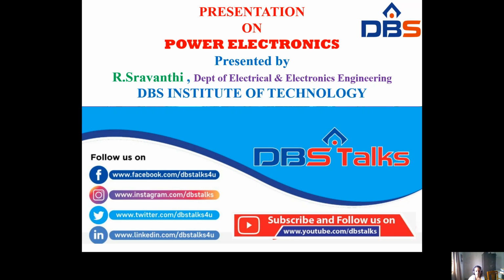Half-wave controlled converter with RLE load and a freewheeling diode. Here you have to see this diagram. Okay. Here single phase half wave control. So half wave control means the circuit diagram will have two thyristors and two diodes. And this is a freewheeling diode and the load will be RLE. Okay, so resistance, inductance and a battery.